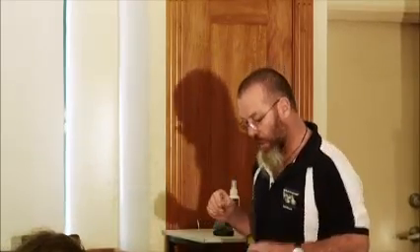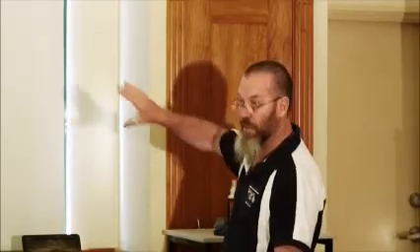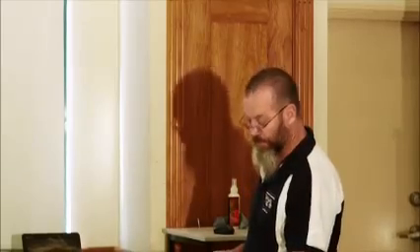You look at N1 tile there, even in the second row, it's just got that little blank in there, and where it's got that blank, that means you just go straight to table 9.4 and get a nominal connection for it. So all you need to do in N1 tile is tie your roof battens down to your roof frame, and everything else is a nominal connection. Okay, it's as simple as that. Where it's just got that little blank there, that means nominal connection.